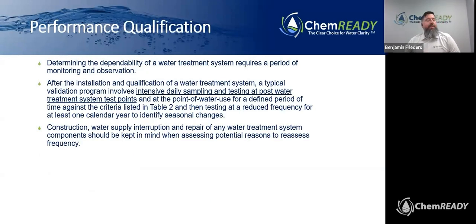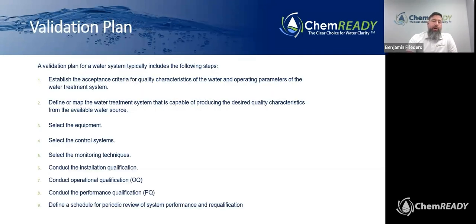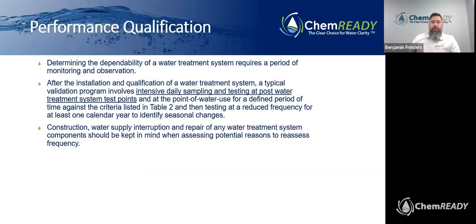So we'll skip over the installation and the operational qualification today. We'll focus just on performance qualification. So when it comes to the performance qualification, what this section in the standard means is there needs to be monitoring in place to verify that your existing critical water system or the system that you just installed are going to meet the specs that you need to meet the standard.